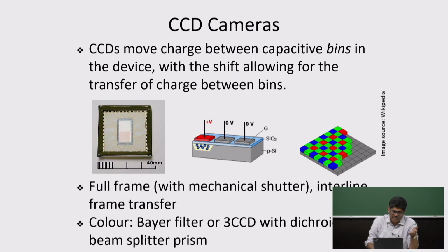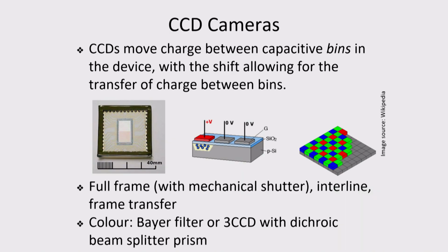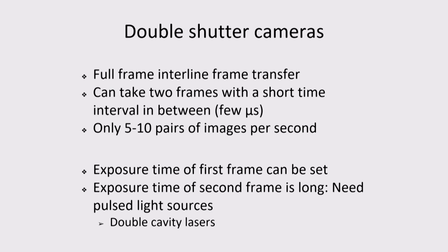Then a CCD camera. A CCD camera is nothing but like a photodiode, you have multiple photodiodes. The light falls on them and is converted into charge. CCD is nothing but charge coupled device. So all the photon intensity is converted into voltage, all that is mapped, and it populates the image.